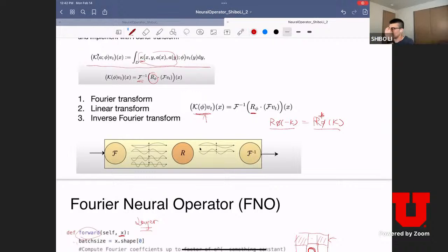What do you mean the whole domain is covered by one period? We don't need to. Because if you discretize, if you do DFT, you're essentially assuming the signal is periodical. There is a theoretical justification for that, but usually we don't concern ourselves about the periodical function constraint in real applications. Standard frequency is defined, I guess, between minus pi to pi or 0 to pi, and they just do some linear transformation to this domain, right? Right.